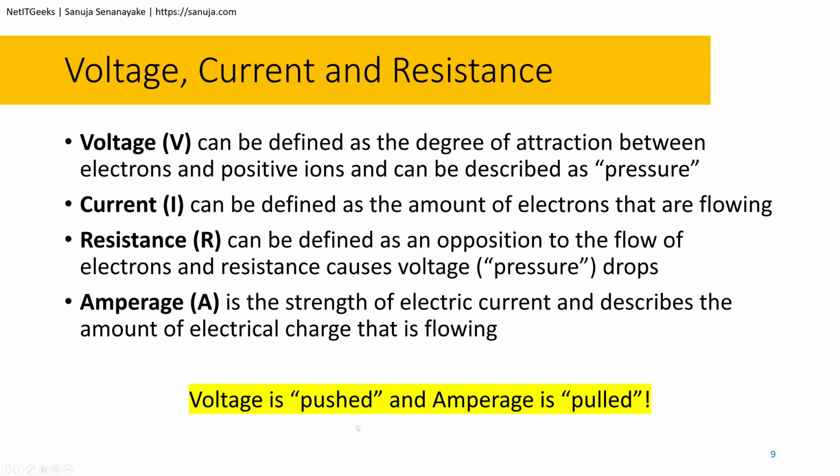But if you connect a lower amp rated device to a higher amp rated power source, it's not going to burn out, because the device will only pull enough amperage to run itself. So a power source with high amperage is just fine. But if you have a power source with high voltage and a device only capable of lower voltage operation, your device will burn out.